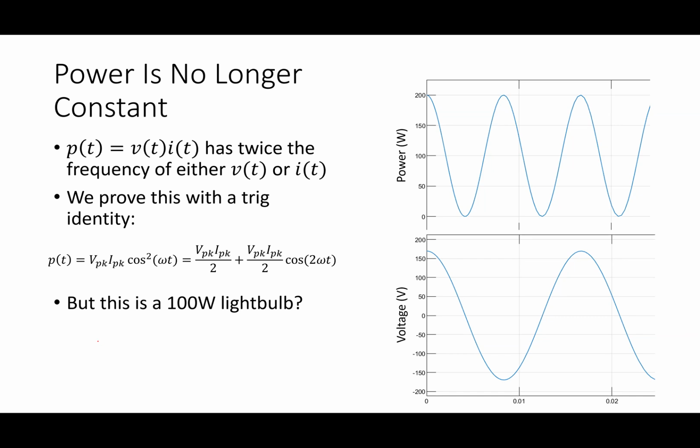So what we looked at last time, I basically said, what happens if I have a 100-watt light bulb and I hook it up to a voltage source? And this voltage source is going to be 120 volts RMS, root mean squared. So this means, what's the peak value of this? Yeah, 120 times square root of 2, which works out to about 169, would be the peak value. Yeah, that's A, the amplitude, right?